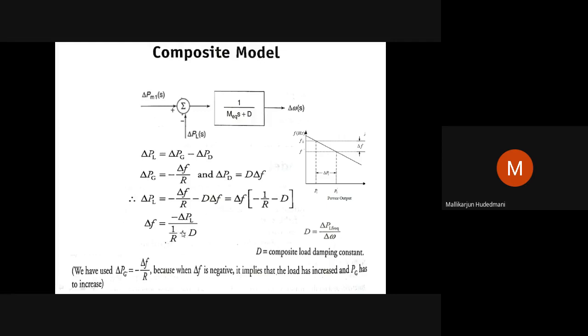So this is how a drop in frequency is noticed. This is observed in the energy control center of a generator. According to the permitted delta F, if it is going beyond the bound, automatically there must be a governing action to address this delta F and bring it within the range. Therefore, this is from a single generator perspective. I have one generator, only R of that, and delta PL of the particular area. Delta F is the change in frequency noticed, and D is the area's D.